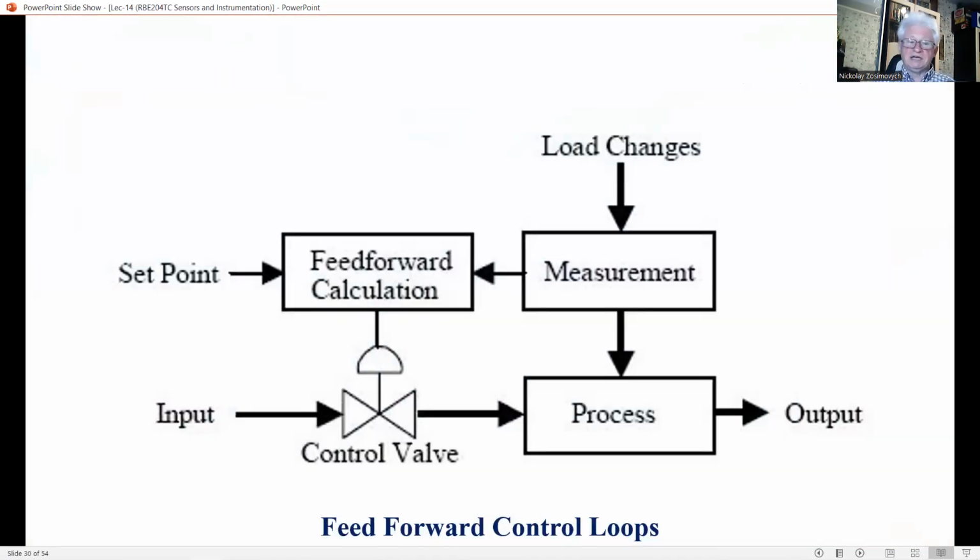Some useful terminology related to control system is listed as follows: plant or process for system to be controlled, input for commands, driving signals, or excitations, known or unknown, output for responses of the system, sensors for devices that measure system variables, like excitations and response, actuators for devices that drive various parts of the system, controller for device that generates the control system signal, control law for relation or scheme according to which the control signal is generated, control system for at least the plant and the controller, and may include sensors, signal conditioning, and other components as well.